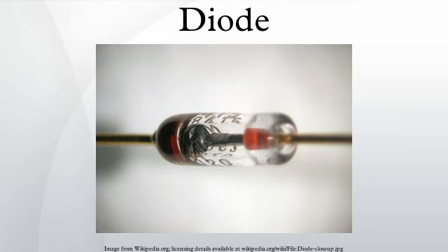With a small forward bias, where only a small forward current is conducted, the current-to-voltage curve is exponential in accordance with the ideal diode equation. There is a definite forward voltage at which the diode starts to conduct significantly. This is called the knee voltage or cut-in voltage and is equal to the barrier potential of the P-N junction. This is a feature of the exponential curve, and is seen more prominently on a current scale more compressed than in the diagram here.